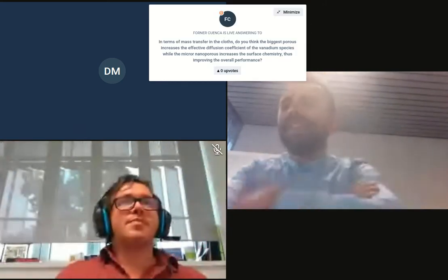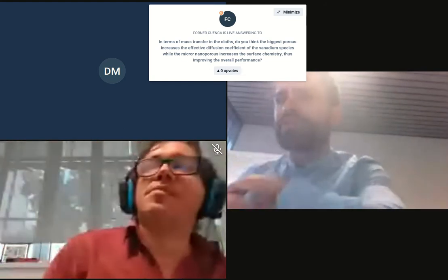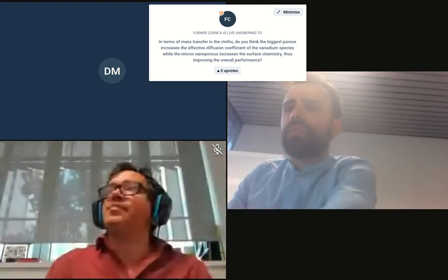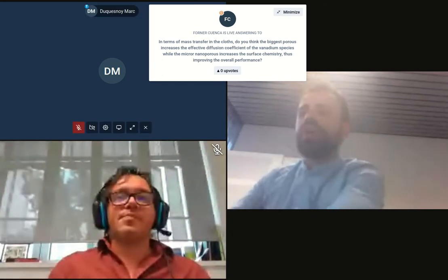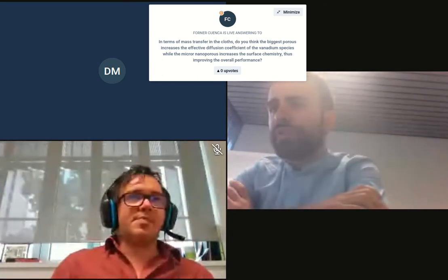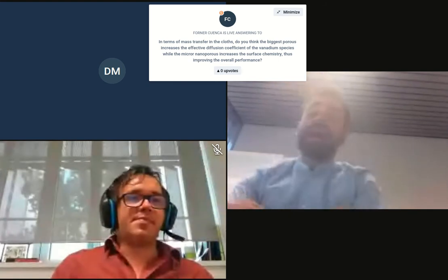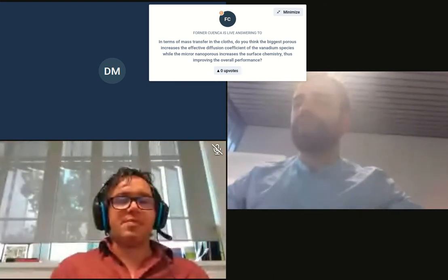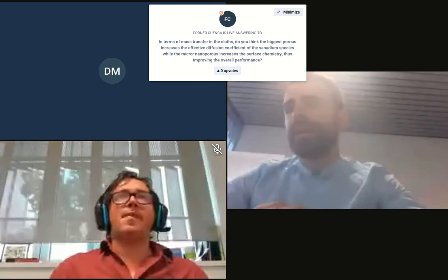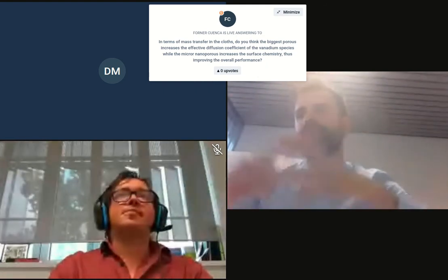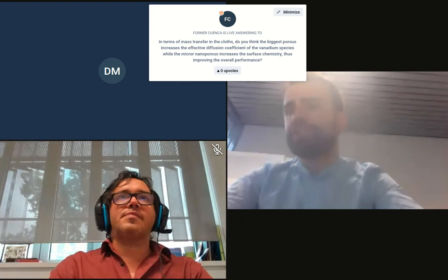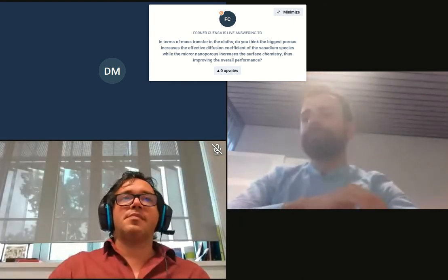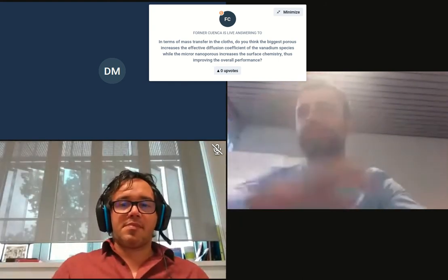Hello, Diana. In terms of mass transfer in the cloths, do you think the biggest pores increase the effective diffusion coefficient of the vanadium species, while the micro and nanopores increase the surface chemistry, thus improving the overall performance? Yeah, I think so. That's a great question. We are still trying to understand that. It's a hard problem because you have different length scales, but we believe that the large pores will serve as convective highways.